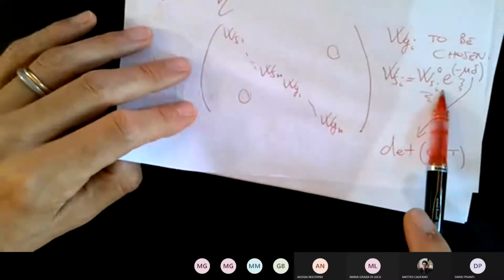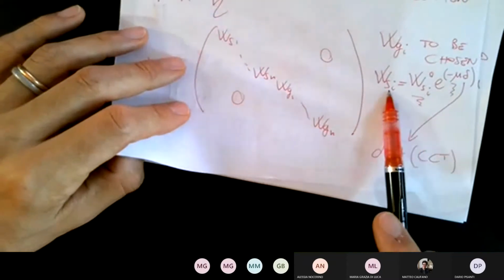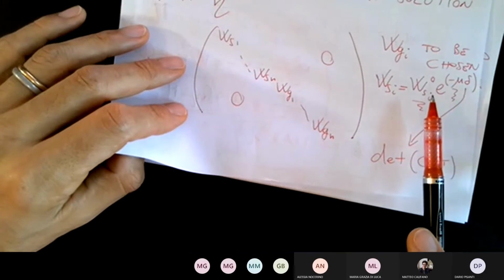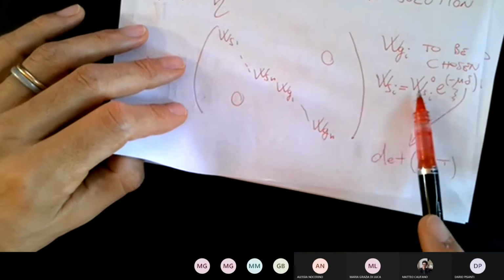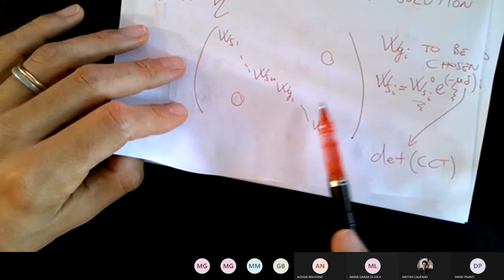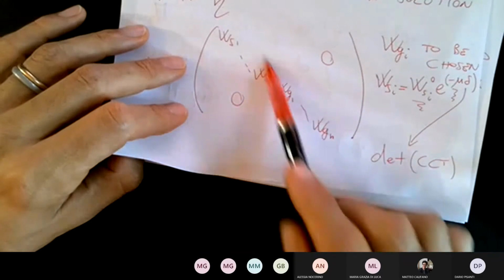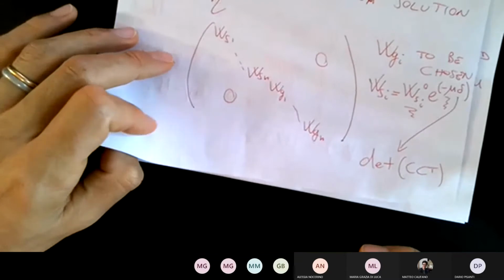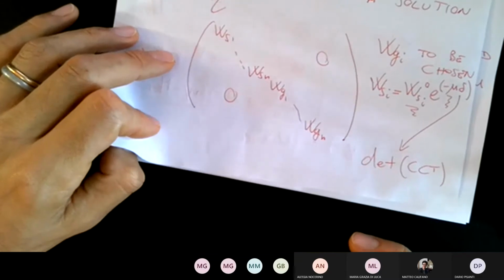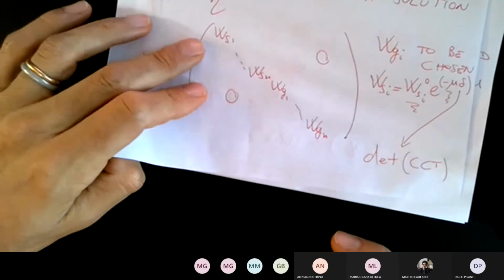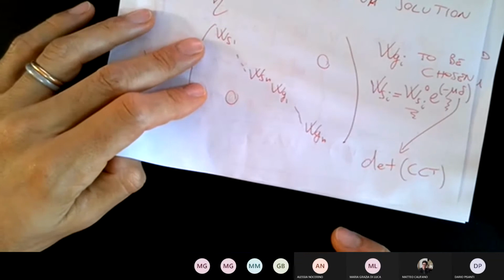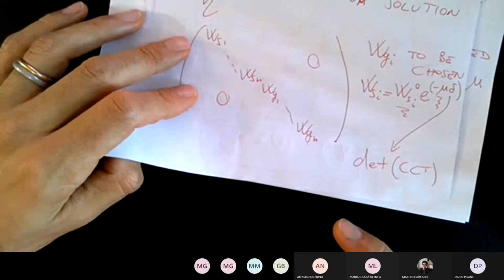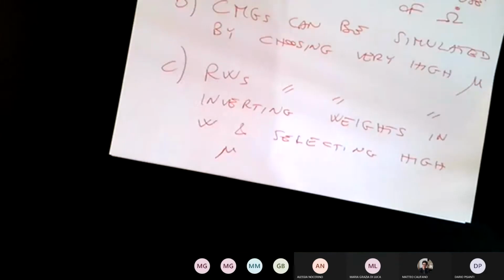So you can do it in many different ways. I mean, the choice of calling the weights for S as function of delta for the reaction wheels, you can basically throw that away and just say that the gimbal weights are 0 pretty much, and so you only retain the weights for the wheels, what we call WSs, but we keep them constant. We just choose some values for them because that's what we want to use.